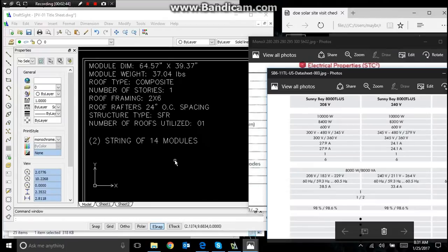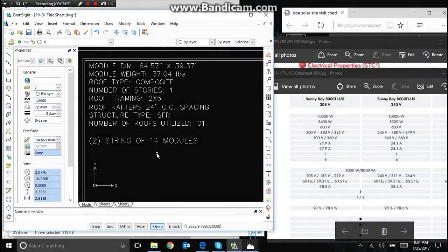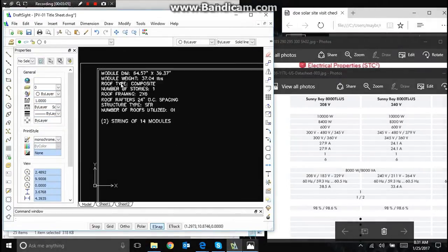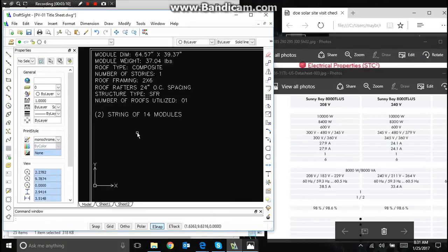We have now the number one, maximum panel modules per string, and number two, we have the strings balanced. So we want the strings balanced to have the same number of panels, or very near the same number of panels in each string. Okay, this will make the inverter more efficient. So that's my mentality for stringing. We now have the stringing for this project, and we can build our electrical diagram as such.